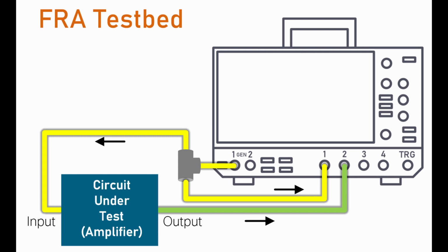This sort of analysis requires that the waveform generator output also be coupled to an input on the scope, so that the amplifier input becomes a reference of both phase and amplitude to compare with the amplifier output. At higher frequencies than audio, the length of the cable will matter as well.